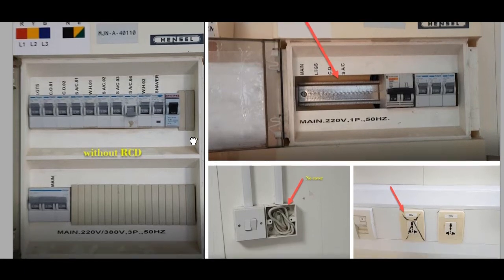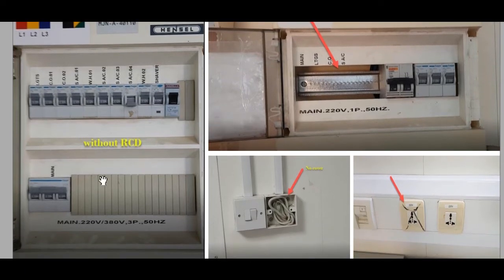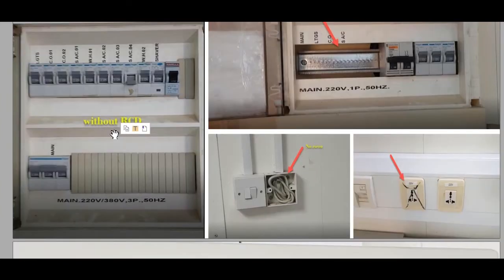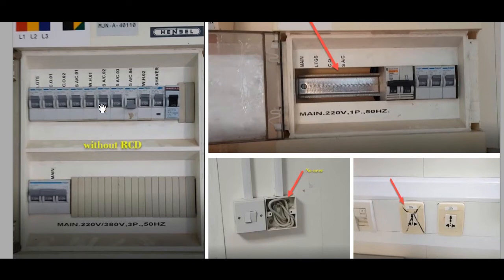For example, here, this is for accommodation, and we don't have RCD. This panel is without RCD wire, they use only MCB here, and it is not allowed because this is for the accommodation room. So there must be a residual current device here to protect the room.